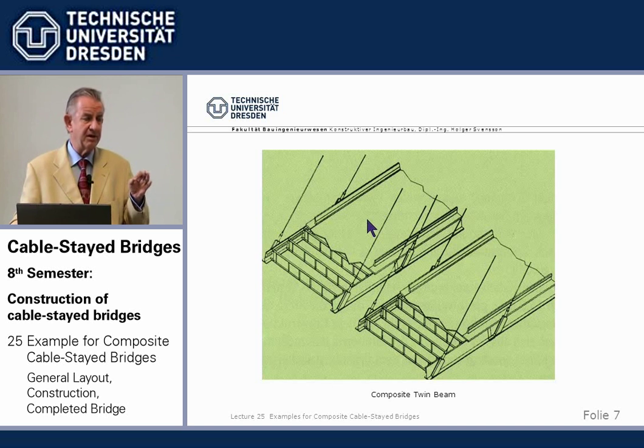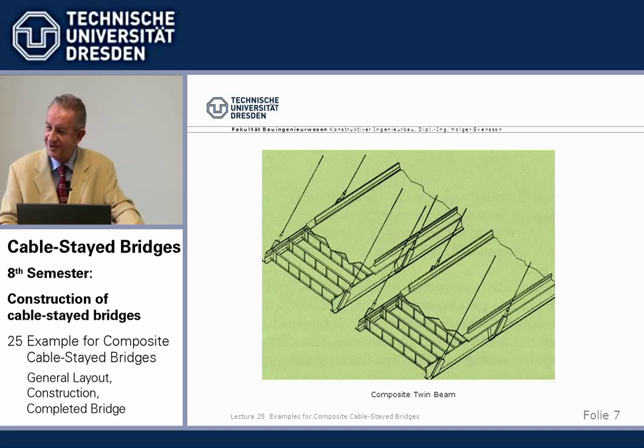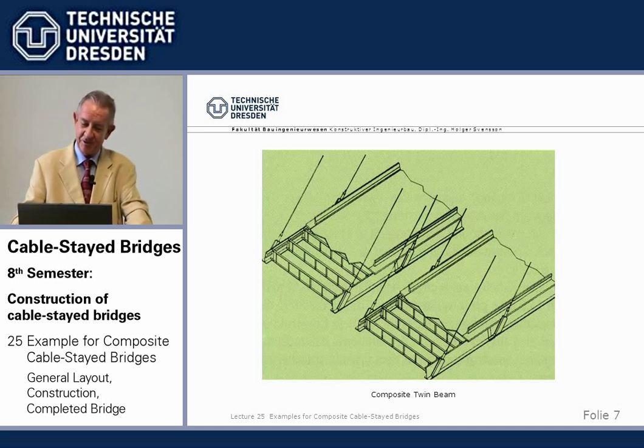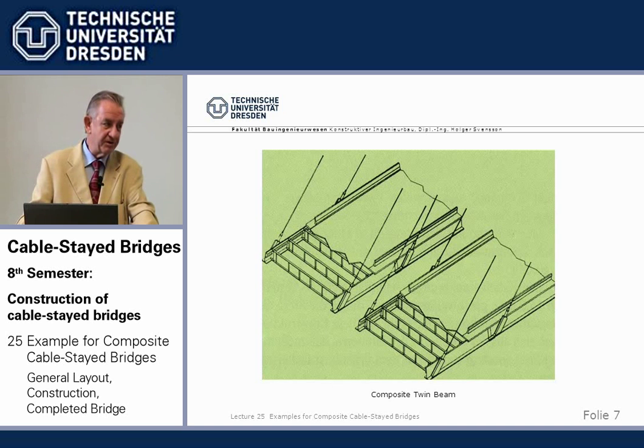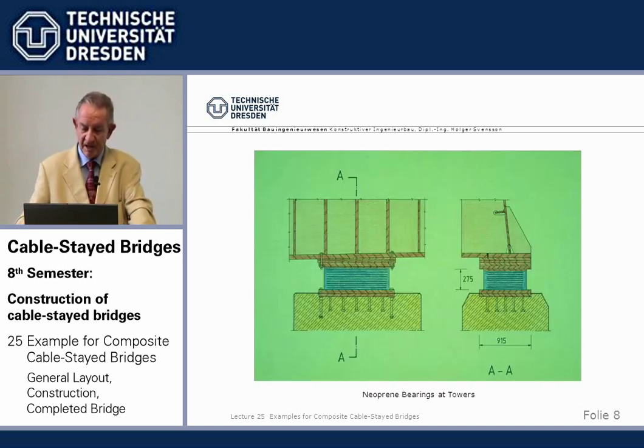So you cannot make boxes and things, these funny modern things. We don't do that in the US. We use open steel sections and bolt them together. We've done it all the time, works very well. So then we have a concrete deck, and there we considered cast in place or precast, we will see. Now, how to take, say, the horizontal loads over the length of the bridge, mainly braking, wind longitudinal.